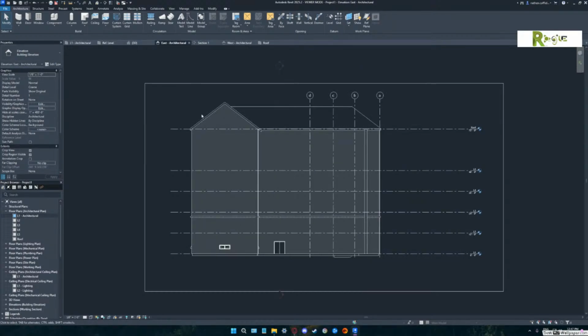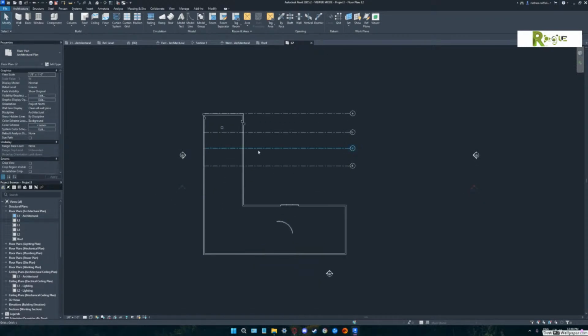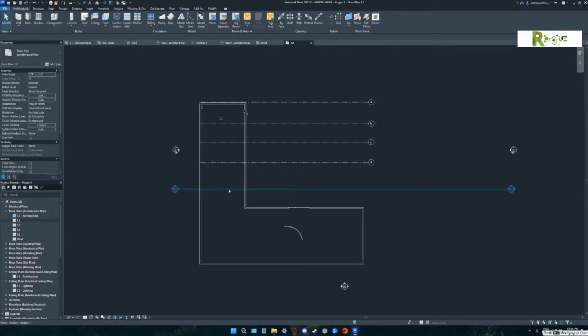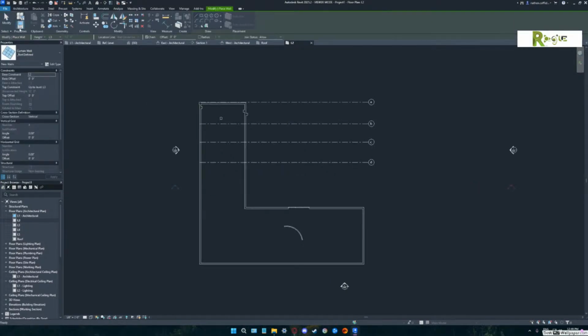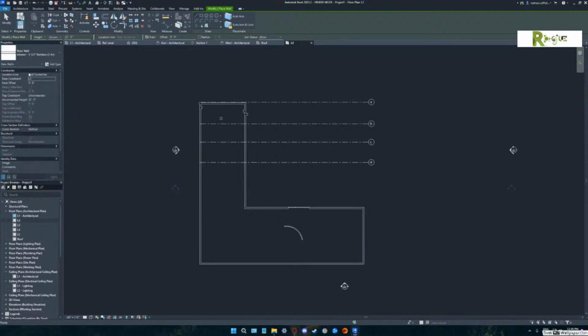So what you would do is over in the browser, you would double click on the L2 and that would take you to that floor, that level. And I can start editing from here. Right there, I want you to draw in some interior walls, make a hallway, make some different type rooms. And then what we'll do is we'll name those.